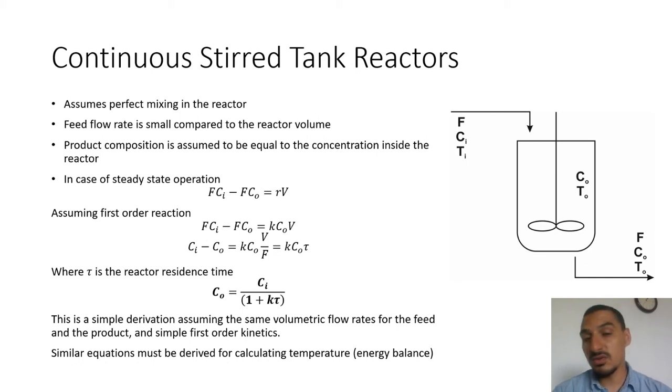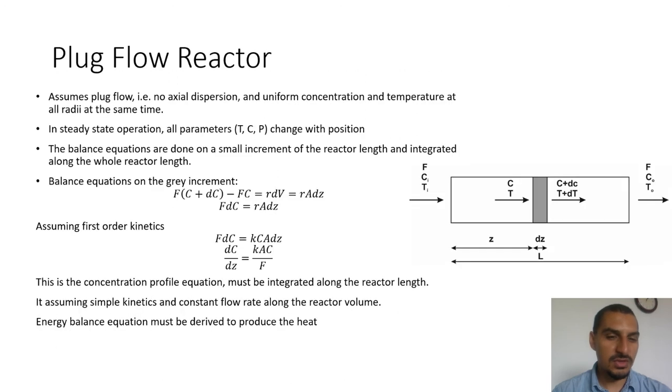It may include the term of cooling or heating, and that may include heat transfer calculations. If you have a coil inside, you have to calculate the Reynolds number, the heat transfer coefficient, and then do the heat transfer calculations. So it's not an easy task. I'm not saying this because we are going to do this manually, but just to appreciate what the software is doing. This is one important point to keep in mind.